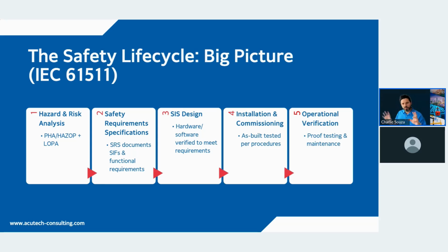And again, the message I want everyone to get out of this presentation is: what you decided in LOPA, do you have that in the field? What you installed in the field is what you've requested in LOPA, right? Are your credits achievable, have they been achieved? Are they real? And last will be the operational phase, operational verification with periodic proof testing and maintenance activities.